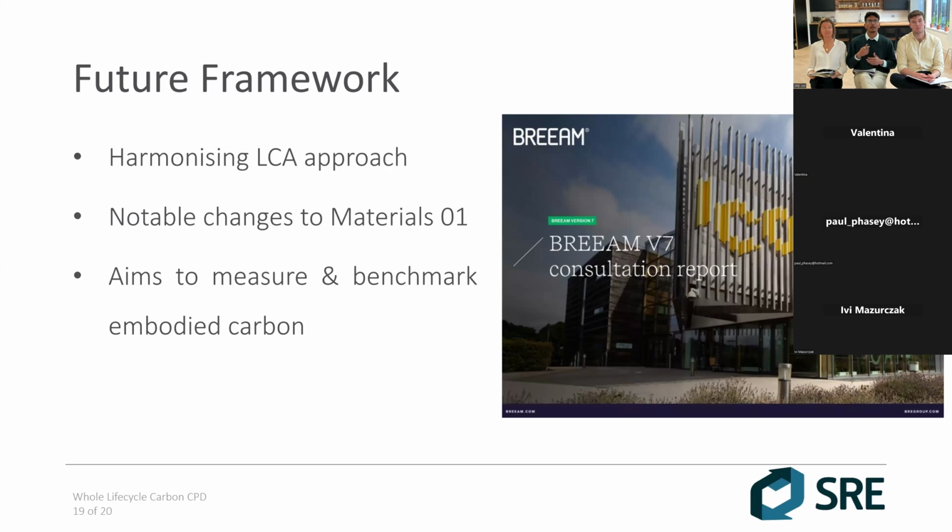Most of you might know that BREEAM certifications are a planning requirement in most of the local authorities across the UK, and BREEAM methodology is undergoing a massive update later this year. They are integrating consistent carbon measurements and whole life carbon assessments, which will be notably reflected in the materials criteria of BREEAM. This harmonization of LCAs in the BREEAM methodology helps them track the net zero approach or a net zero pathway of a building, which will enable all the assessors to measure and benchmark their embodied carbon.